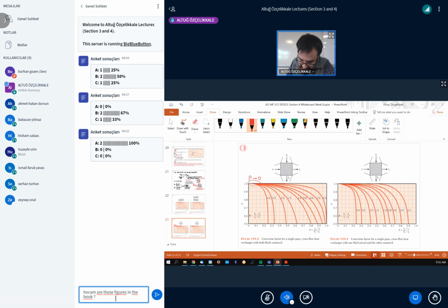If you extend this line, you are going to see that when R is equal to 0, we are actually approaching kind of this curve. Both of them, in that case, F is approaching unity. And this one indicates that delta T, small t is going to 0. This one indicates that capital T is going to 0. If you look at the calculation, that's the only way that can happen. And these are corresponding to individually phase change behavior, right?